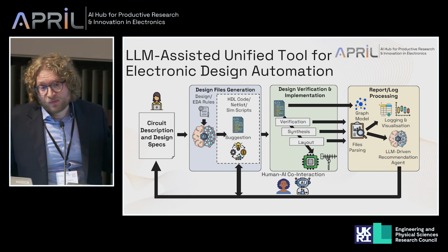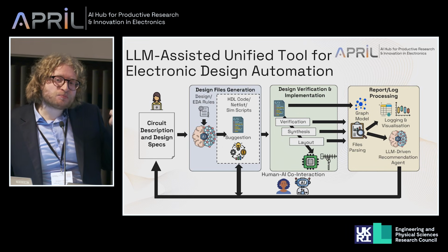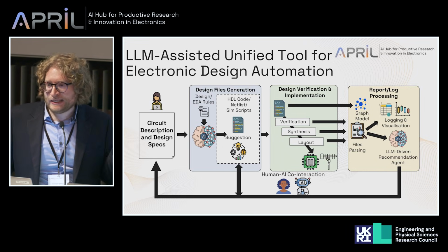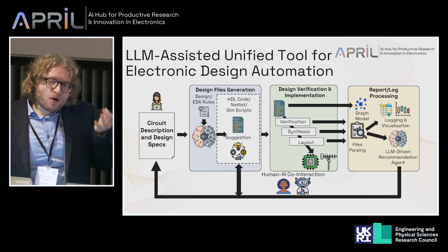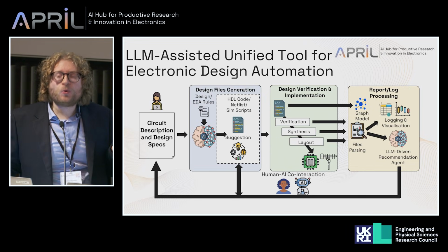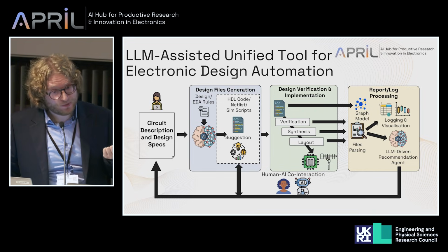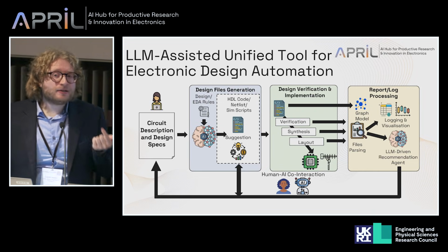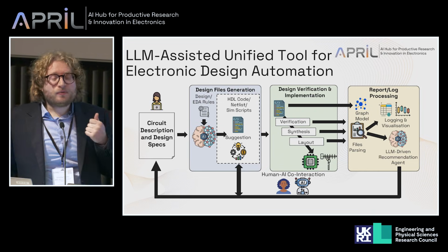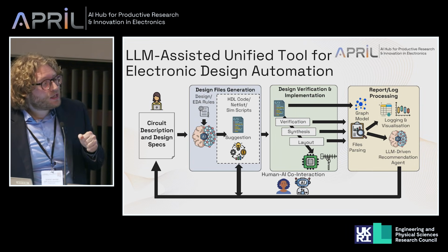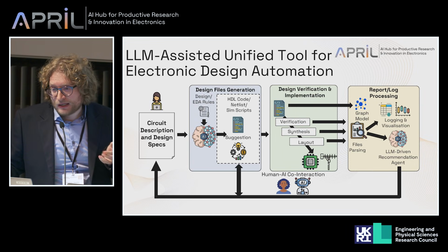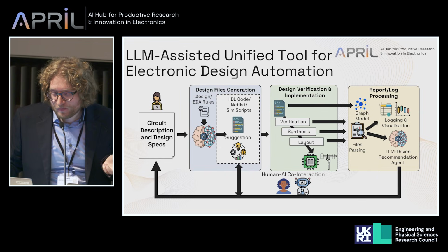The outputs from the large language model are then provided to commercial EDA tools. At the moment, in the tool chain we are proposing, we support tools from AMD, Vivado, for FPGA design, tools from Cadence, Virtuoso, for analog mixed-signal design, and tools for radio frequency design, like ADS from Keysight.